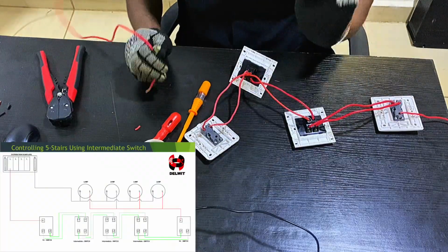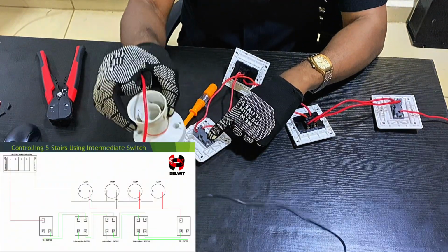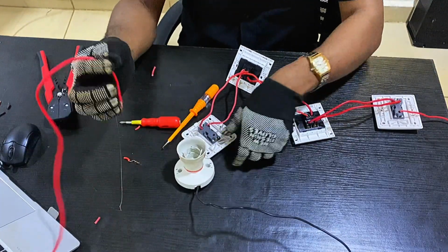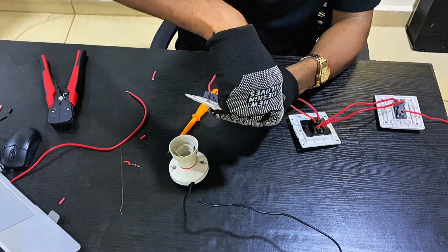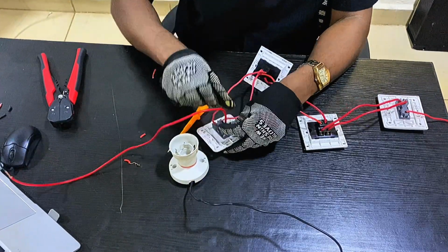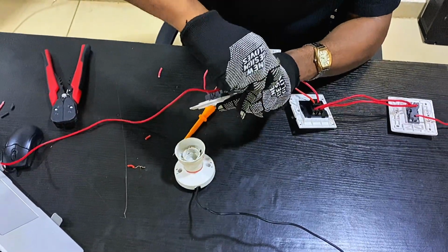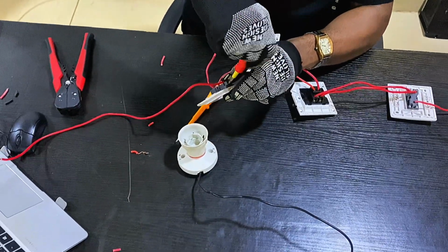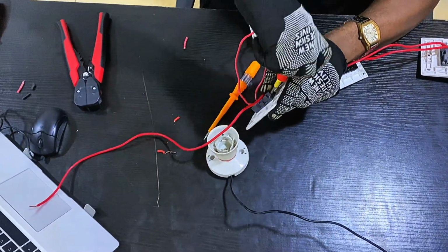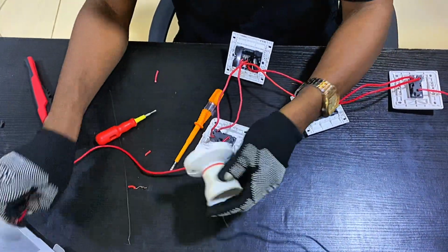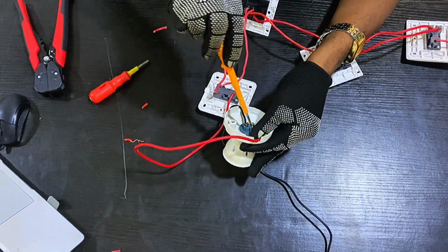All right, so the last aspect now is to connect the common of the last one gang two-way switch to the live of your first lighting point. So this is the common of the last one gang switch. You connect it from the common, take it there. This is the common point. Screw it properly and tightly. Remember that this is on the wall where your normal switch is. Connect it. Ensure that they are very tight. Then you go to the lamp itself, and connect your lamp to that position.